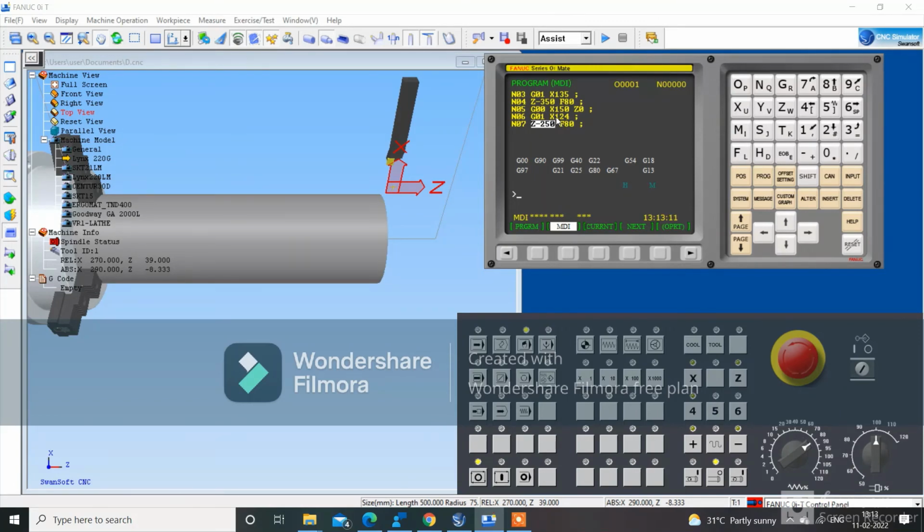At the same time, x124 is given here. It means we are reducing the diameter from 150 to 124. I mean, before that we have reduced it here to 135 two times, so two turning operations. So these are the keys that you have to read from here. That's all. And it's a 9-line program. So we are running the program.